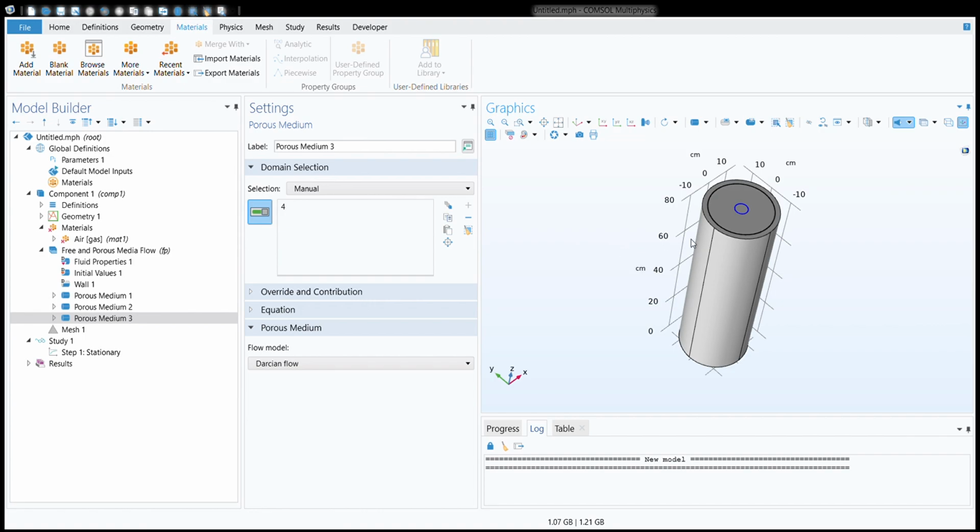Now we can also make the hole here itself for the center pipe. For that we have to create a cylinder again of radius 2.5 centimeters, height 120 centimeters, from the z-axis minus 20. If you build all objects, something like this will pop out.